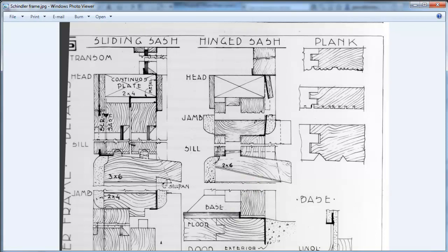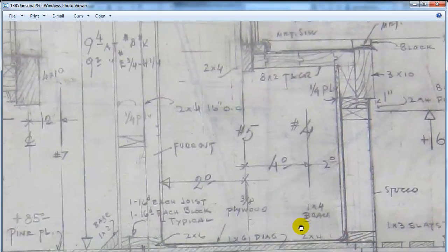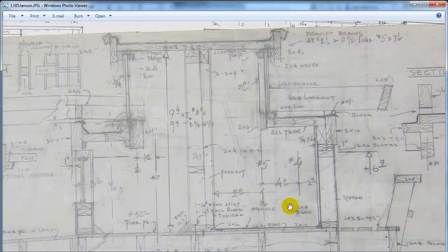Okay, another example you can take a look at is, let's pop this up, the Jansen house. This is an example of the Schindler system being used in place. You see in this drawing a lot of the same details called out specifically for how it was going to be implemented here. There's the basic wall system, and that funny detail in the corner where we put a little triangular base. This is the clerestory condition with a wooden wall, the transom window, a little bit of beam underneath it, and some planking over here forming a bit of a ceiling. Just the clerestory area.